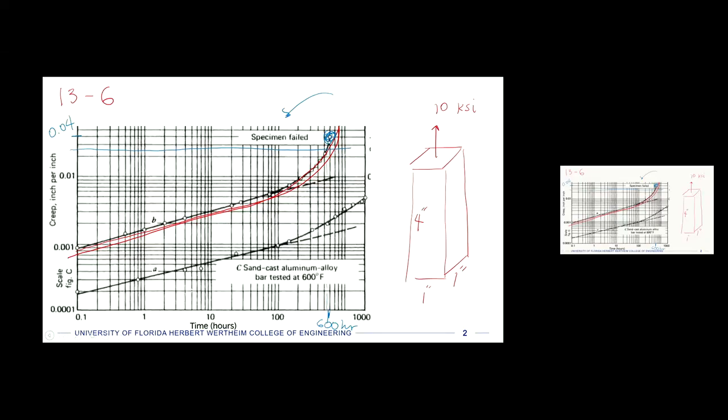So all we know is the specimen failed at that top point. And so if we want to avoid failure and we know a limiting strain of 0.025, then we use that. We say we calculated the parameter and we toggled between time and temperature to get how many times we could do that.